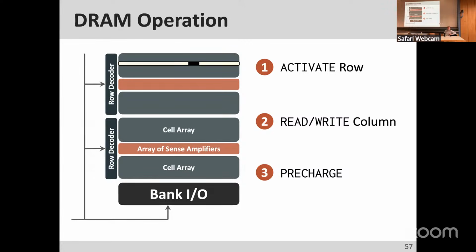Yes, absolutely. They're wider, they're thicker. There are a lot of signal integrity concerns internally in designing these things, and DRAM manufacturers are very, very good at that. One of the other issues with DRAM processes is that they need to be thicker. As a result, you cannot have many of them. And also, you don't have a lot of metal layers to add interconnects because of the fabrication process. It's not as good as logic process today. As a result, you need to be very careful in the design of these things.